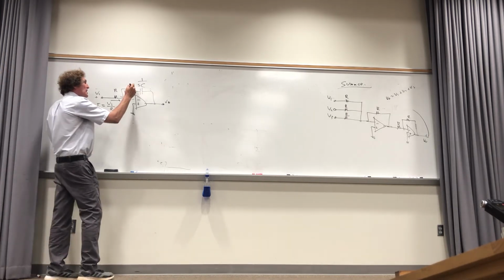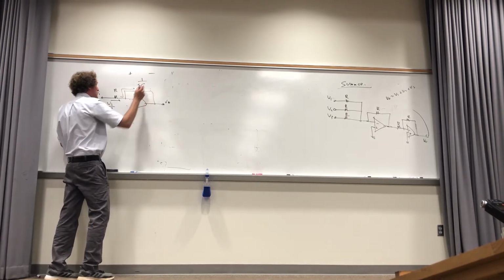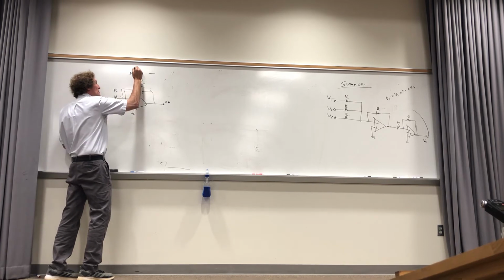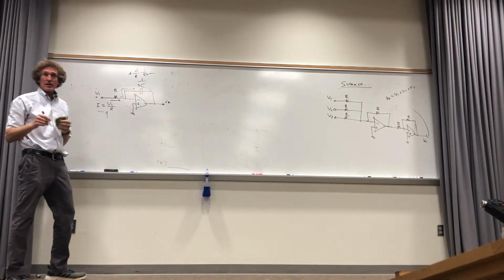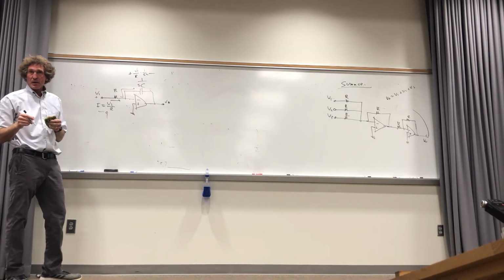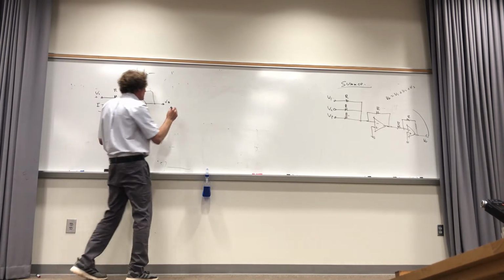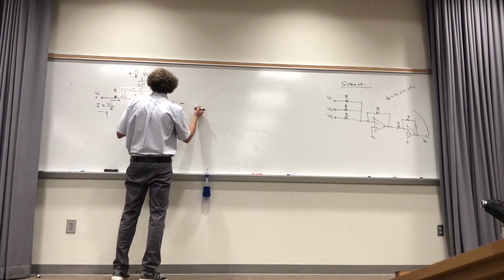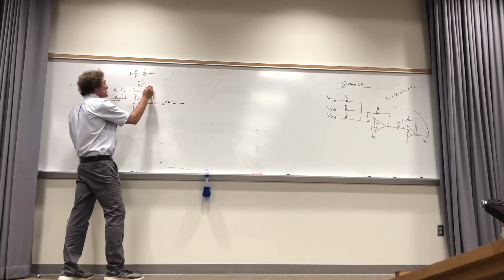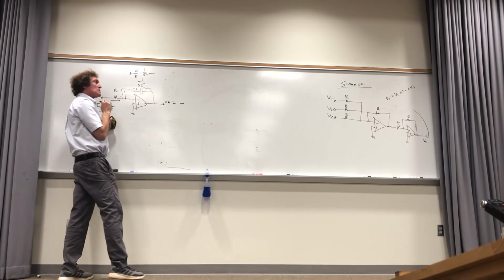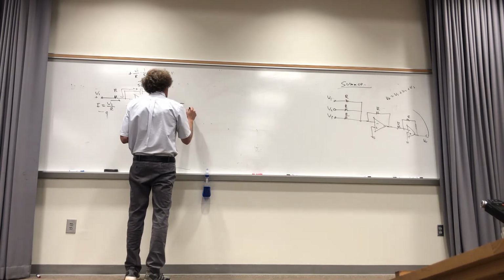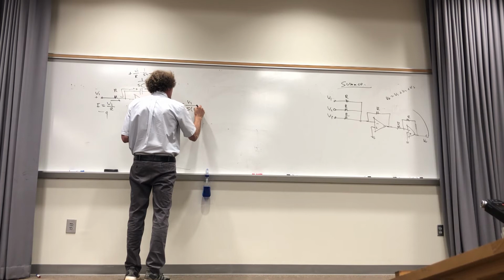All that current flows here. It means it develops a voltage here that's equal to this I, or V1 over R, times 1 over SC, correct? Right? It also means that the voltage output here is minus that, because this is ground and this is a voltage drop, plus to minus that value. Do you agree, everyone? So that voltage output is minus V1 over S times RC.